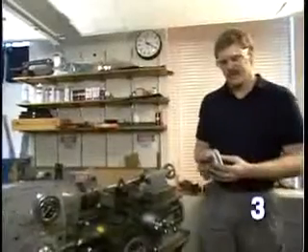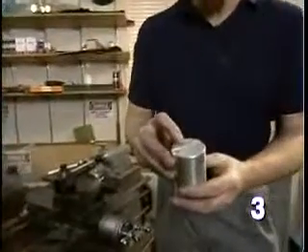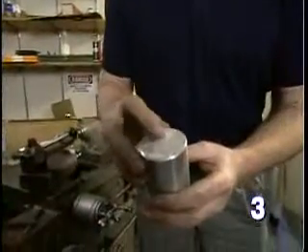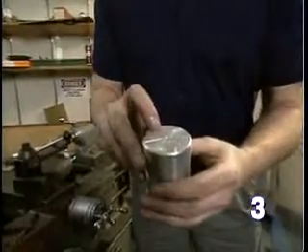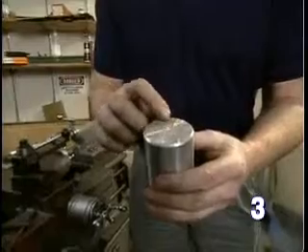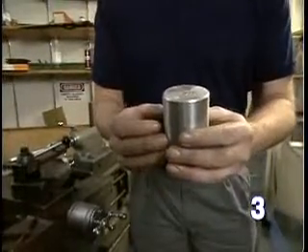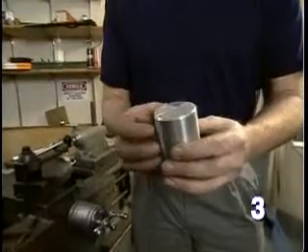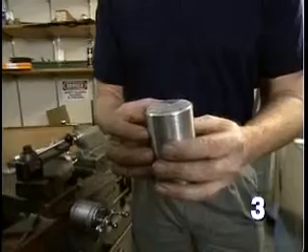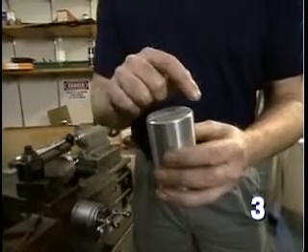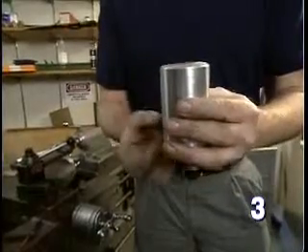I have just cut this piece of stock from a larger piece of bar stock. Used a bandsaw. So you can see here that I've cut it reasonably square to the sides of the stock. The surface is rough and it is not completely perpendicular to the side of the stock. So I'm now going to put this in the lathe and face the end of this part. And in doing that, I'll produce a very smooth, flat surface that is also perpendicular to the sides of the part.